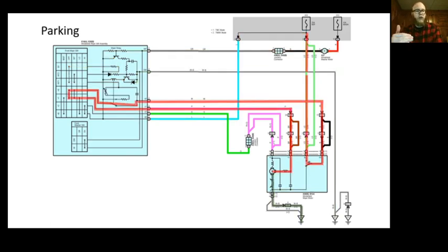It's going to park the wipers, and because of this switch right here, it's going to send current through here. And even though my switch is off, and it's connected just like that, it sends power to this field coil and the brush until the wiper motor comes around and the switch comes back down.